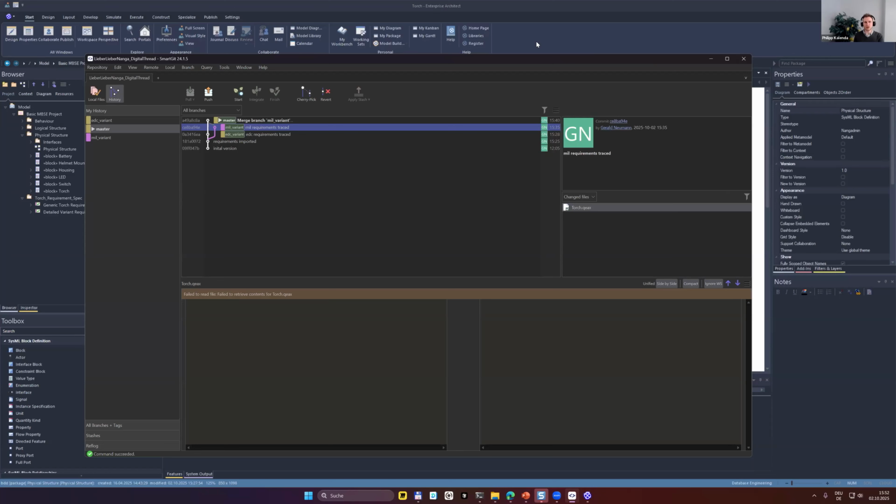So rebasing the variant branch onto the main, the base, and then you can pull certain changes from the base into the branch. And if you do a visual merge, then you even have the control of what you pull, and maybe not do an auto merge to pull everything automatically. Then you have better control of what to integrate from the base into the variant branch.